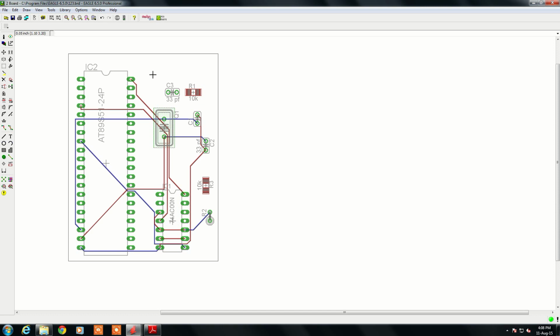Once you design your circuit diagram, then you can draw the ground plane. Ground plane means now in your PCB there is some space left, where we can use this place for filling the ground. That means the remaining empty space should be used for filling. That is called polygon draw. Your ground should be as big as possible, so that it will have low impedance for the return currents.